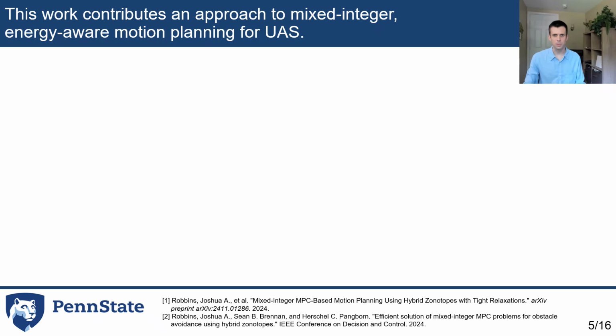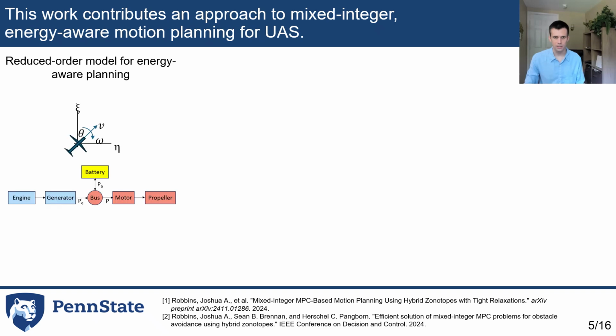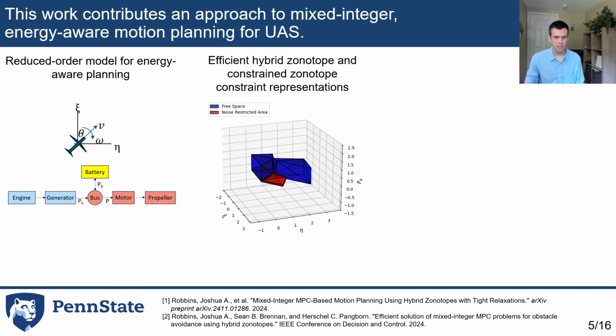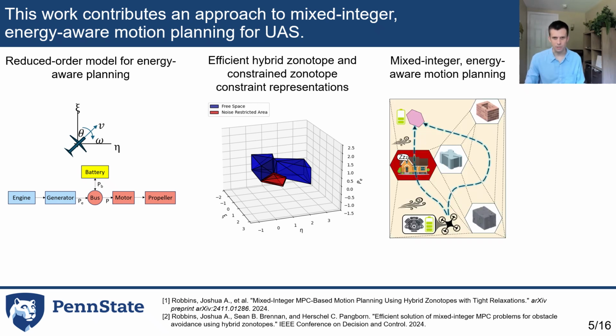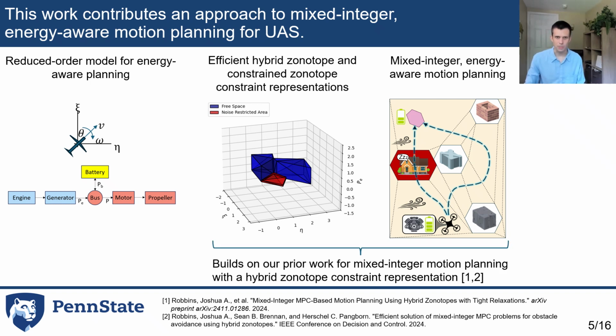So our work contributes an approach to mixed integer energy-aware motion planning for UAS. Our contributions include a reduced order model for energy-aware motion planning, efficient hybrid zonotope and constrained zonotope constraint representations, and a mixed integer energy-aware motion planner. So the second and third contributions here build upon some of our prior work for mixed integer motion planning with a hybrid zonotope constraint representation.